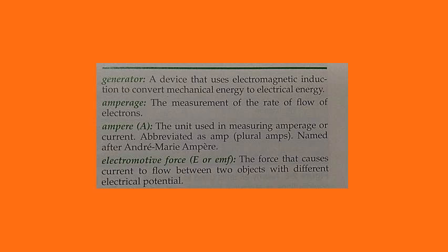Power. Power, represented by capital P, is the rate of doing work, and in electricity is measured in watts, represented by capital W, or volt amperes, VAs. Power determines how fast a certain amount of work can be done, or how fast a certain amount of energy is consumed by a load. Watts are relatively small units, and we often speak in terms of kilowatts, that is per 1,000 watts, and megawatts, that is per million watts.